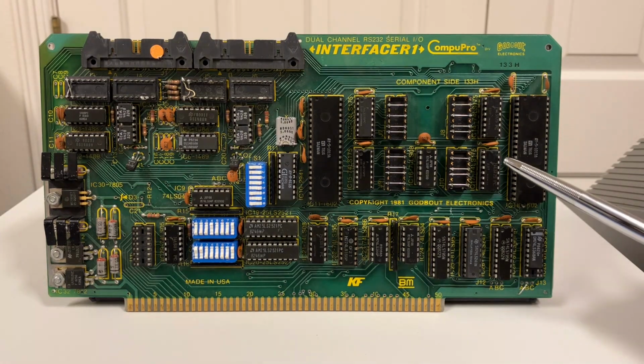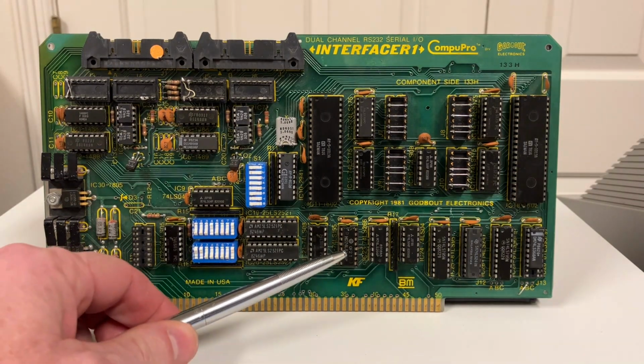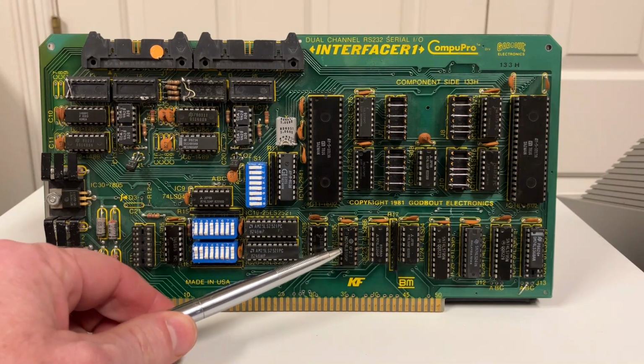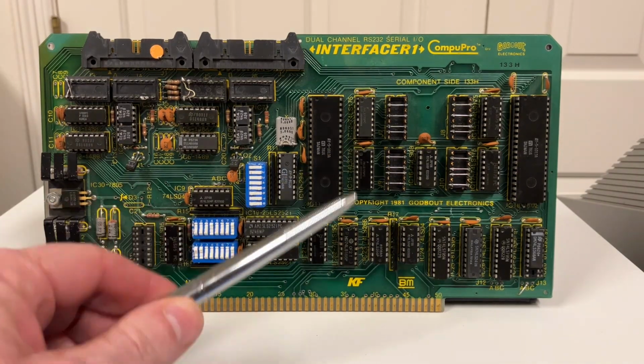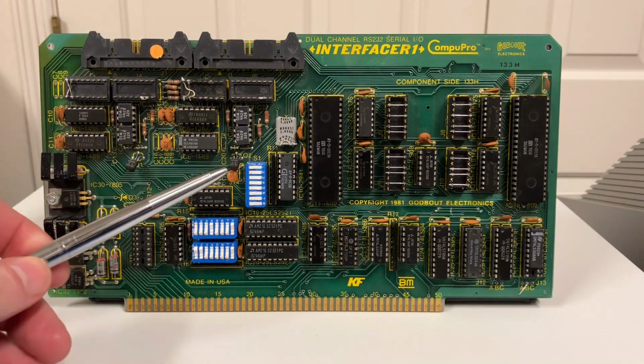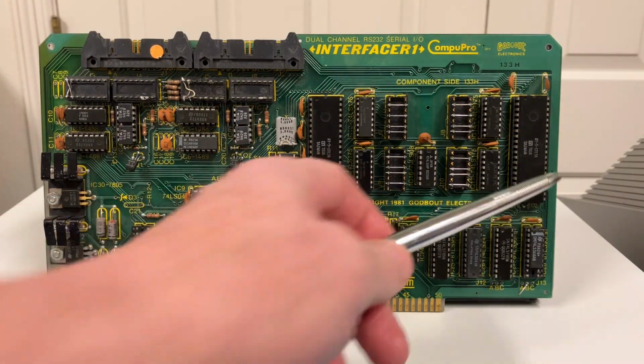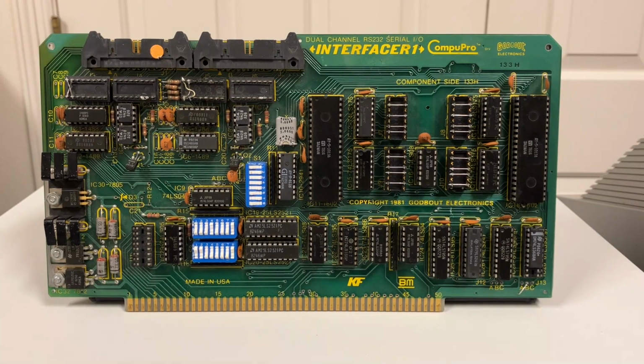So we need to disable writes to these flip-flops. And so I did that by lifting a pin out of a socket to disable that down here on this chip. One pin is lifted to prevent writes to the port 1. One pin is lifted to prevent writes to the second port on that. So that way they always behave exactly like we expected with those wired jumpers. All right, the last thing we need to do is get the baud rates right. So the top 4 switches set port A, the bottom 4 set port B. So of course I have port B set for 300 baud like we need for cassette.